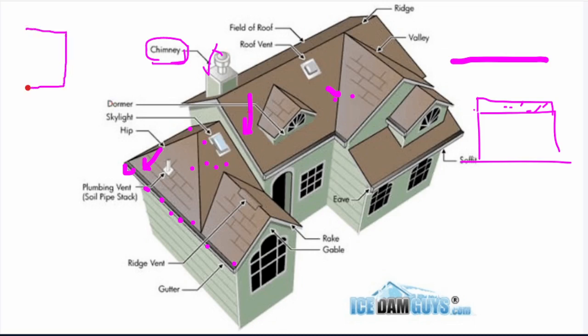So in your plan, you have some ducts. Am I right? So these ducts, I need to see all of them on the roof. All of them will come like that, at least 50 centimeters up from the roof. We need to see them. This is another critical problem that we have to know and somehow respect. And look here, at least 30 centimeters, depending on the project maybe 1 meter, should be the distance between